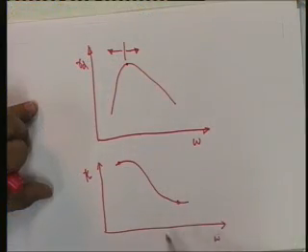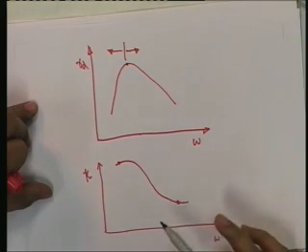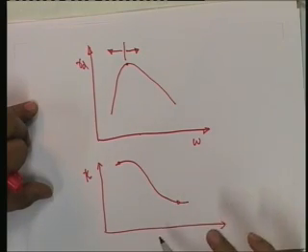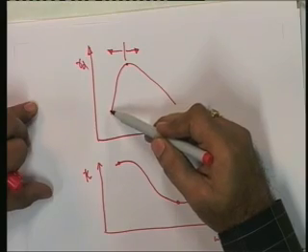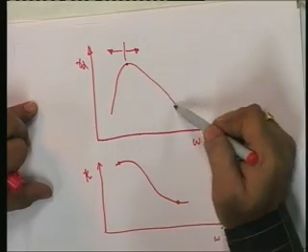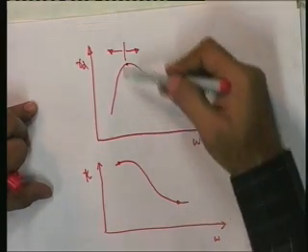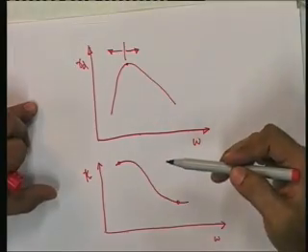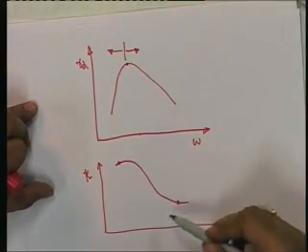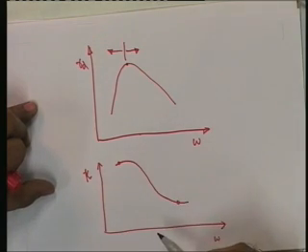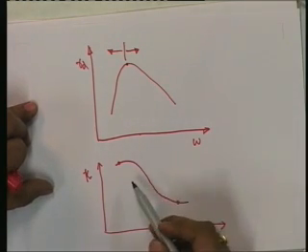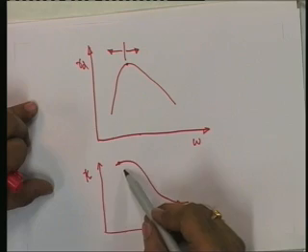So, what is happening is that as we increase the water content, for example in the compaction process, the orientation of the particles changes. That is, the structure is gradually transforming from flocculent to a dispersed structure. As we increase the compactive effort, this also shows that on the dry side of optimum the permeability value will also be less.